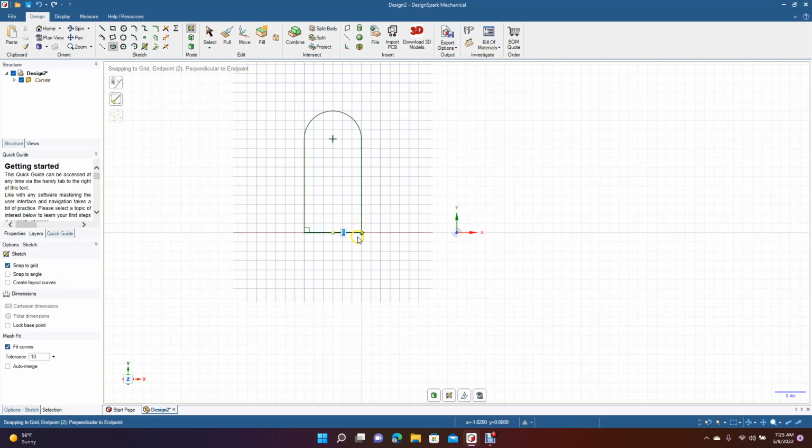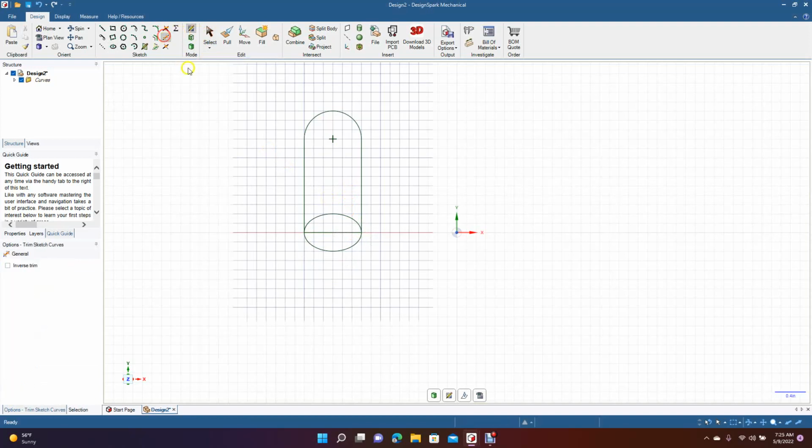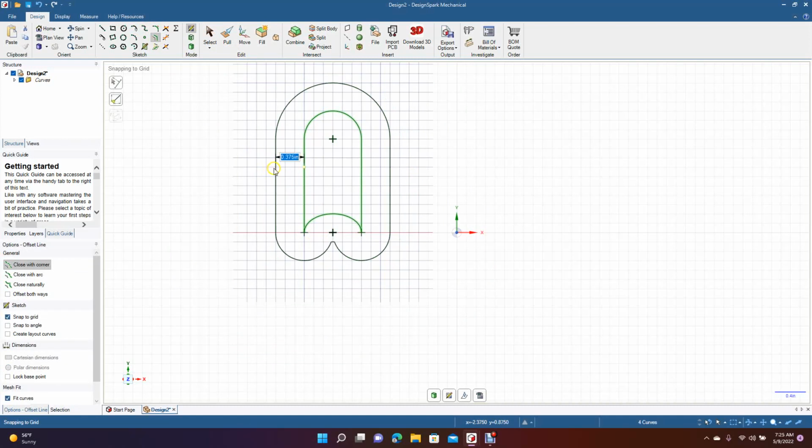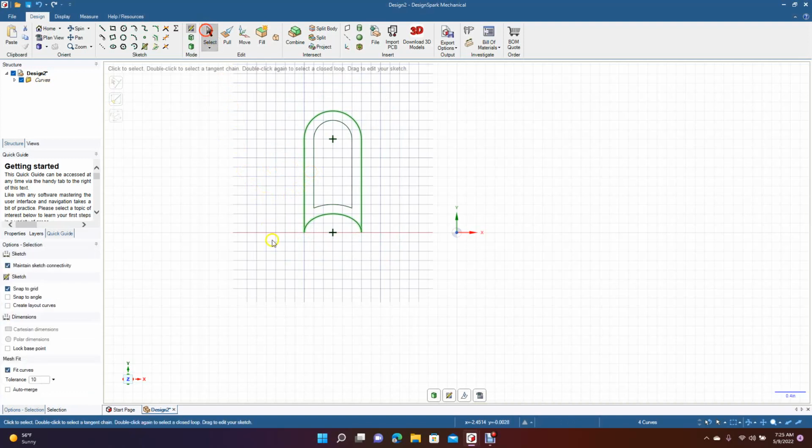And now you have the option to elongate or make your ellipse narrow, or if you wanted to cut into that shape there, you go ahead and go to there. You get your trim away tool. Now you have this kind of shape. Then you could go ahead and do your offset. You can offset in, or you could offset out. So now you have this kind of shape.